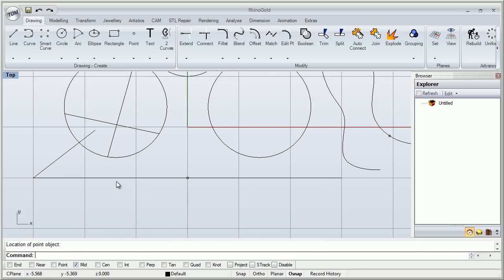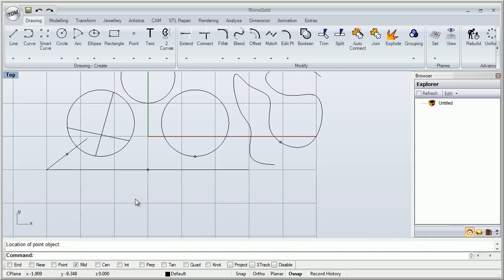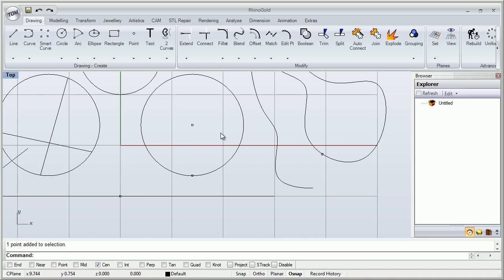Now let's carry on with this one. It's more interesting. Center, we use it when we want to find the center of a closed curve. Remember, the curve must be closed to find the center. There's no center in open curves. We put my cursor next to the exterior part of my line, and the small word Cen appears. That means if I click, this point will appear in the middle of my center. It also works with an ellipse.